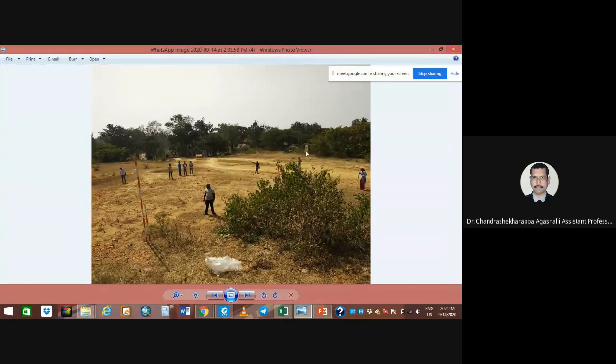Okay, and this area we are going to divide into different blocks. That's the area dividing. I told you that you can do it triangular, but here triangular is not going to work. You are going to do 10 meter by 10 meter gridding. First you take the corner, the border outline of this 50 meter by 50 meter area. That is your area, and within that, you need to establish 5 lines, and another 5 lines. So you will get the 10 by 10. How many will you get there? 100 grids.